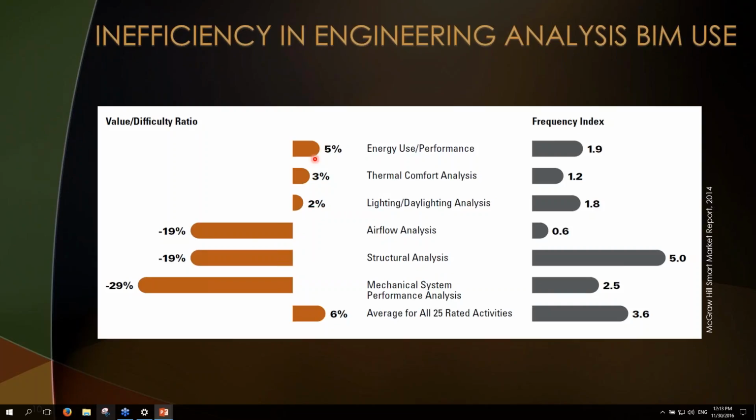If you look at that, they are either very low or even negative in some cases, such as structure analysis, MEP system, airflow. It means that, as a designer, it's more efficient to create an analytical model from scratch instead of using your BIM model. You have to spend a lot of time creating the model and then coordinating it with the BIM model to make sure your model is correct.